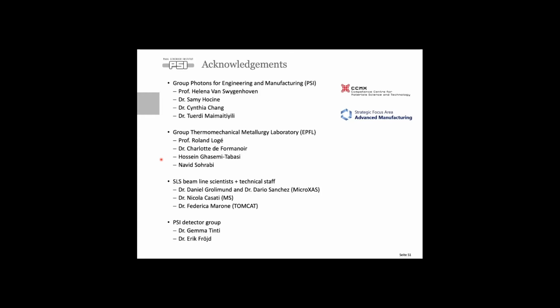Local melting. Can you actually detect the edge of the melt pool? I've seen this in the papers from Tony Rollett's group, that in some materials they can really detect the edge of the melt pool. With nickel it's not so easy, but sometimes you can really see where the solid-liquid interface is moving. This is where the crack is starting. So that sounds and looks very much like solidification cracking, right?